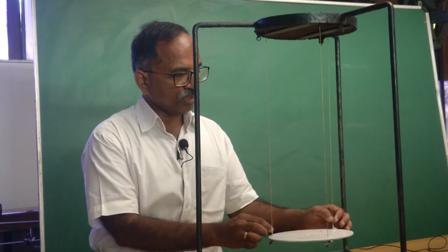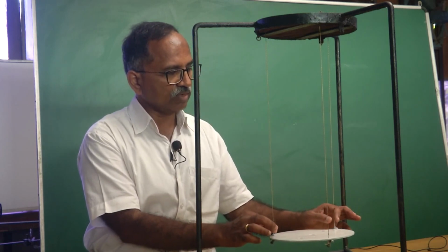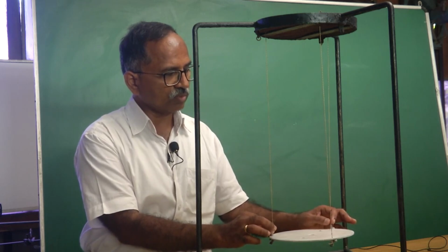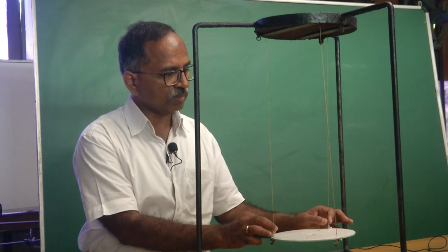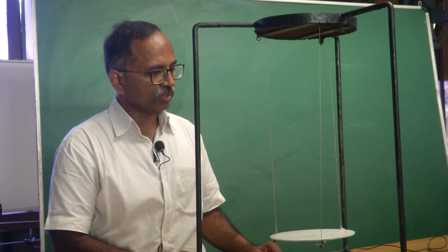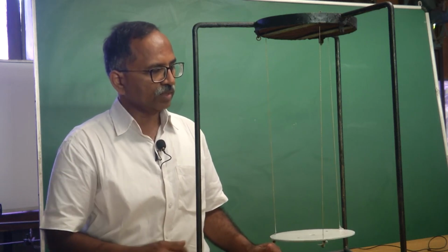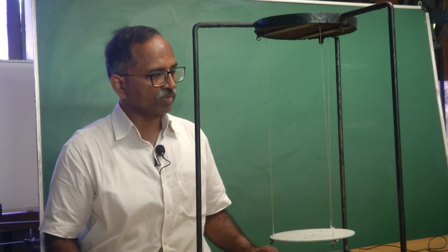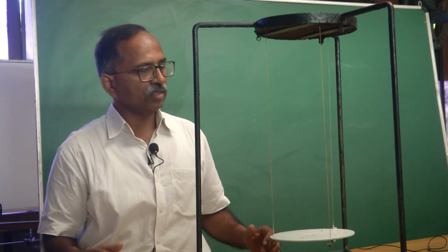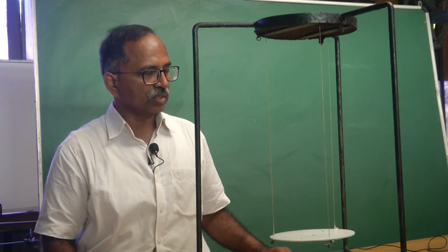Now, you may notice that if you consider this as its steady mean equilibrium position, and I give a gentle angular twist to the disc and tilt it a bit in the horizontal plane and then release it from that position, it keeps on swinging back and forth. We all know that when a typical vibratory system is vibrating at one of its natural modes, there is a continuous interchange between the kinetic energy and strain energy or potential energy.